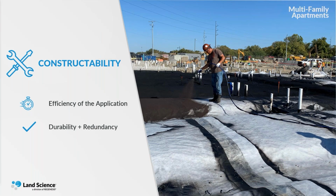And each of our vapor barrier technologies offer a high level of constructability. And that's really a crucial component of any vapor barrier evaluation process. The reinforced grid and the underside geotextiles within our sheet layers, those are designed for optimal durability across a range of substrates and foundation types. And then the multi-layer composite systems offer really the redundancy necessary to withstand the rigors of construction sites.